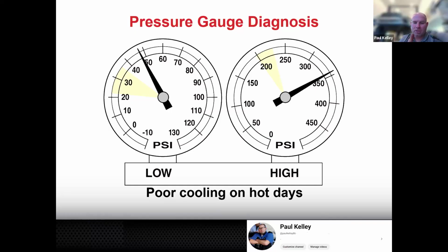So the condenser, absolutely, and the cooling fan, we need to really look at those both very well. If the condenser is full of junk, it's not going to get a lot of airflow. It's not going to be able to get rid of a lot of heat. If the cooling fan is inoperative, it's not going to get airflow. And even if the condenser is in good shape, the cooling fan's not going to help it get rid of its heat.